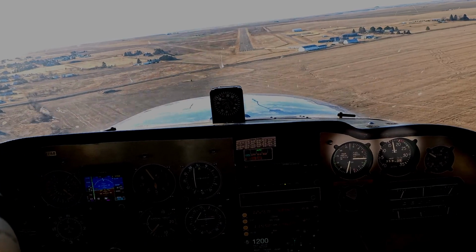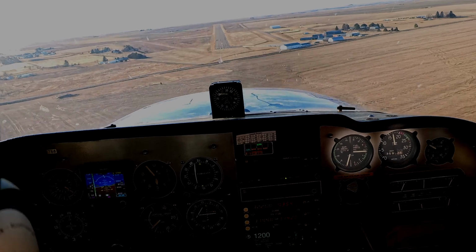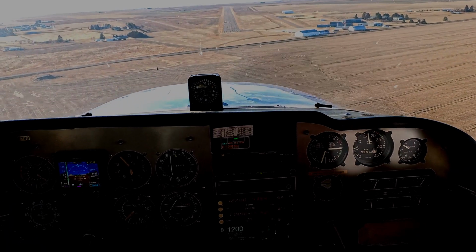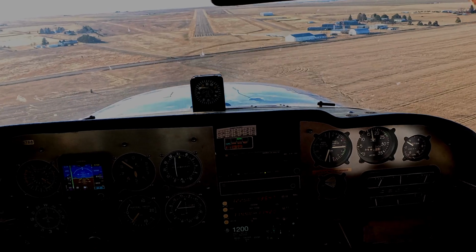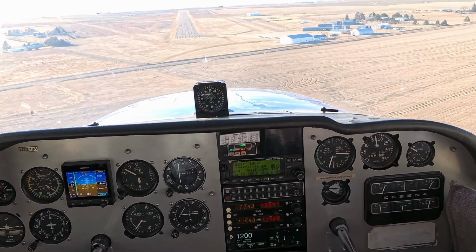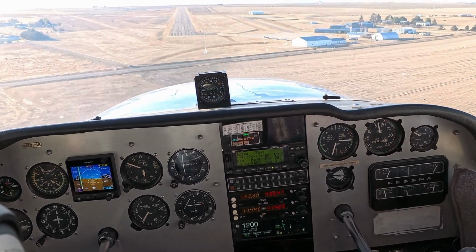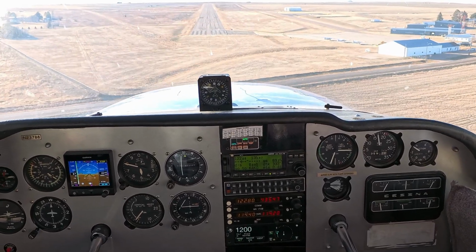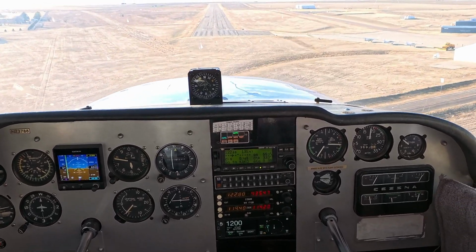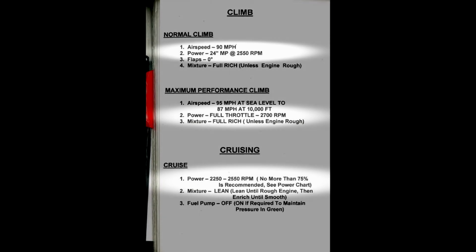In flight, large power reductions, such as power to idle, means you might not be supplying enough power to the engine to sustain the desired RPM. When this occurs, the airplane has gone to the full low pitch setting and there's still not enough power to the engine to achieve the desired RPM setting. As always, follow POH procedures to ensure that you are not operating outside of the limitations of the engine's RPM and manifold pressure settings.